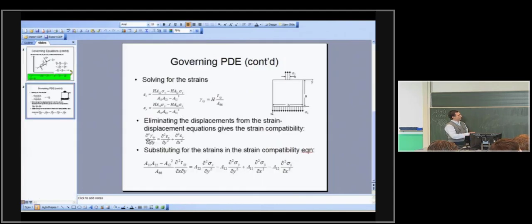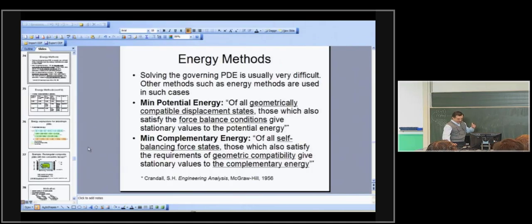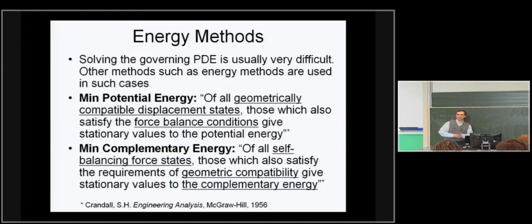For a two-dimensional problem, remember we said last time that if you eliminate the displacements, you can come up with a relationship that combines only the strains. So that is the equivalent of the strain displacement equations. So you can satisfy that exactly, which means you are making a displacement-based solution, which most finite element models actually do. And you can satisfy your geometric boundary conditions.